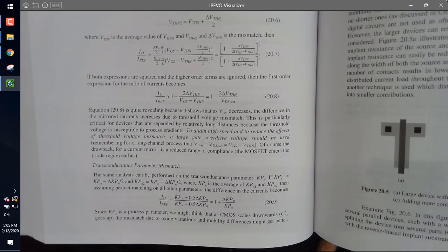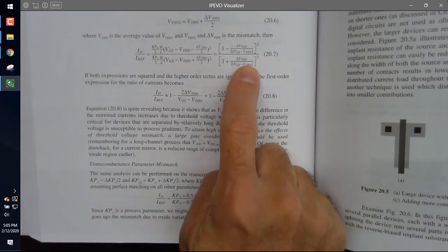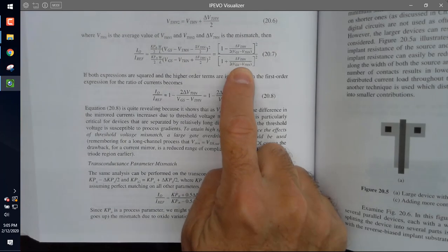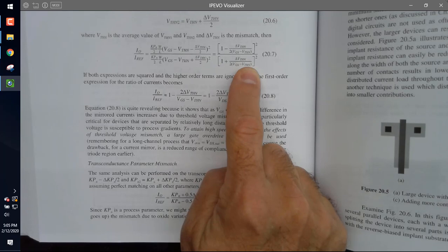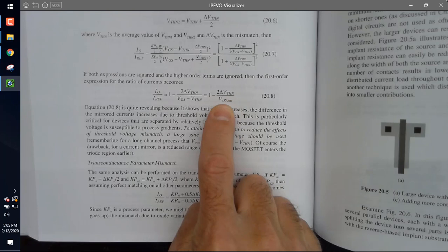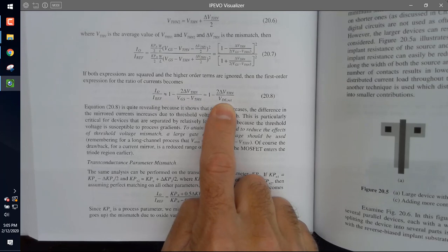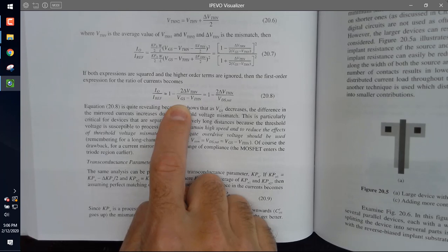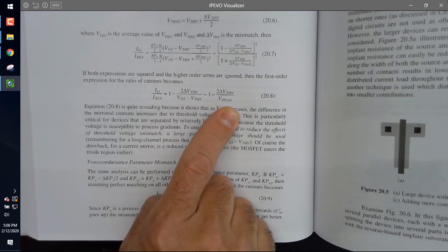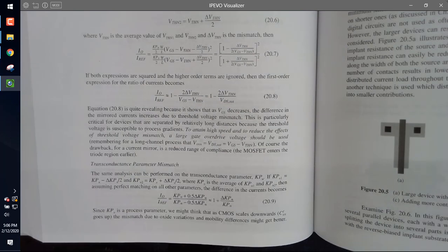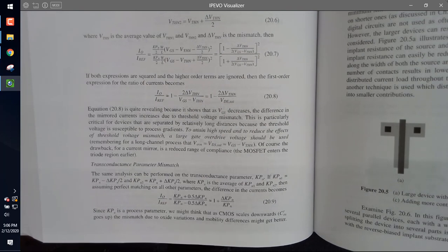All right, so if you can answer that the VGS is large compared to the threshold voltage, that minimizes the mismatch. That's a big one. Notice here there's VDS sat, so if they try to trick you a little bit and ask how you would design with VDS sat or overdrive to minimize mismatch in the current mirror, you would design with large VDS sat. Okay, does everybody see this? Pretty intuitive once you think about it: large VGS, large compared to the threshold voltage.